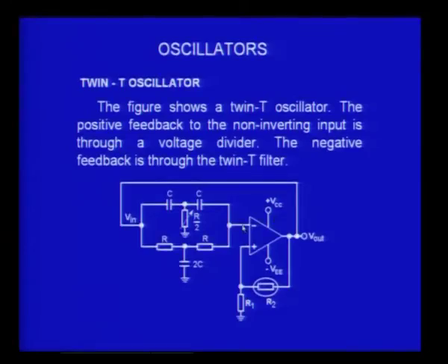So, we have formed a simple oscillator network here, and you can see the circuit is very similar to what we have done in the case of Wien's bridge. We take the output and give it through the twin T network and connect it to the input. So, this is used in the feedback network, with 0 phase shift. Once you do that, you get an oscillator output which is again in the form of a sine wave, and you can see the values of the capacitor and C are given here.